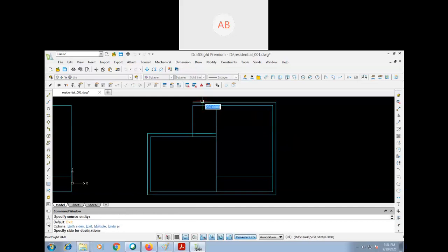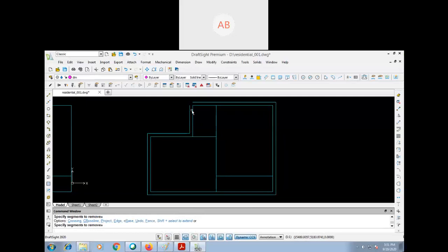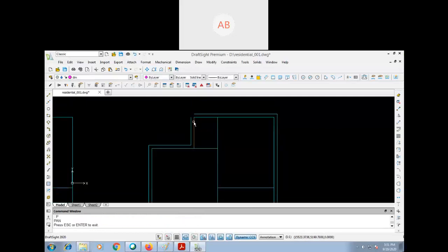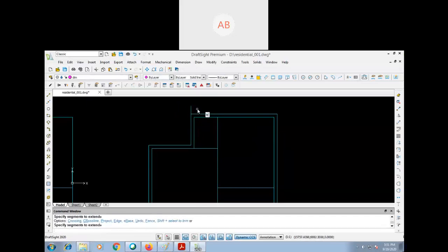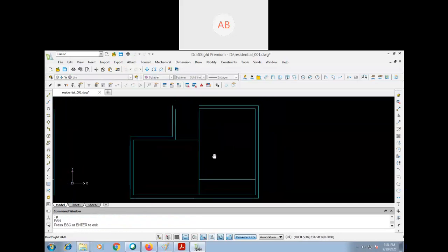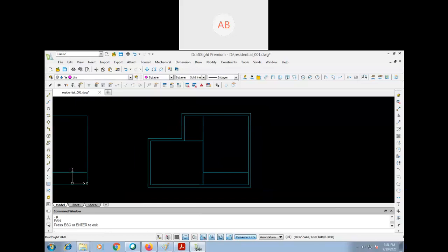This thing also I offset here. I offset it here. Okay. Trim the outside part. I stretch it here. Remember today you heard about stretch. Then extend this part. Then again trim it. So you see, there is no hard and fast rule how you should be drawing. Everyone has their own individual approach. So I am comfortable like this.